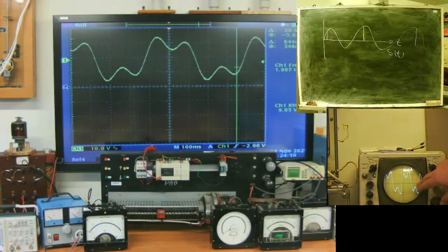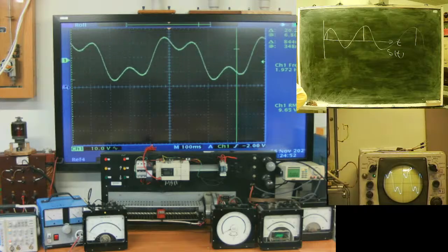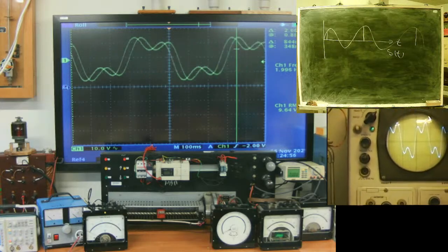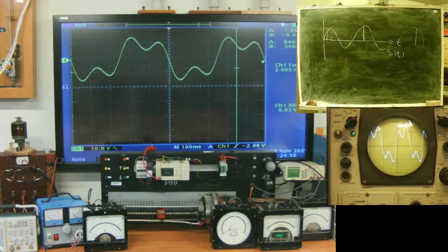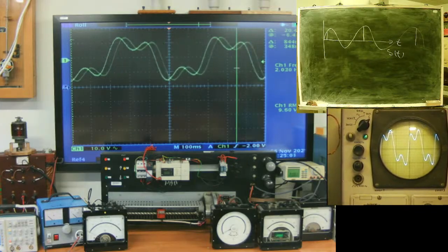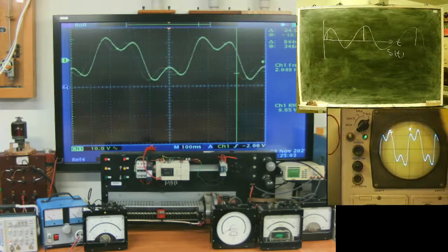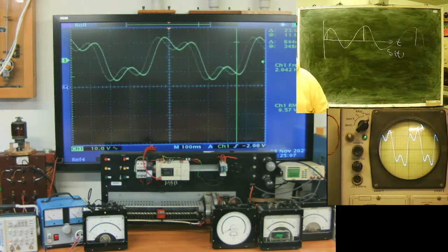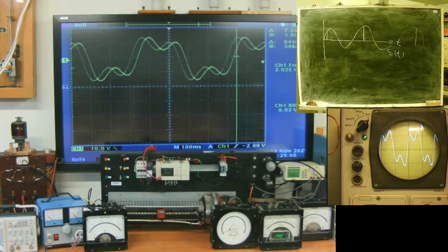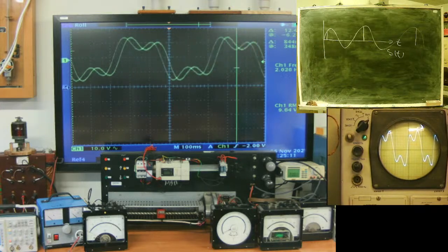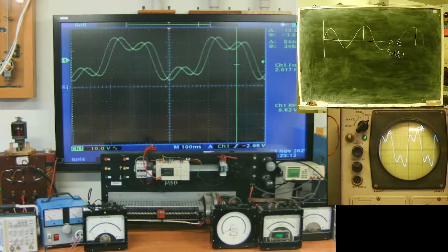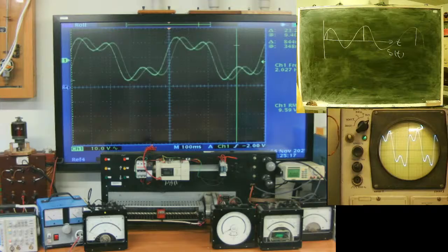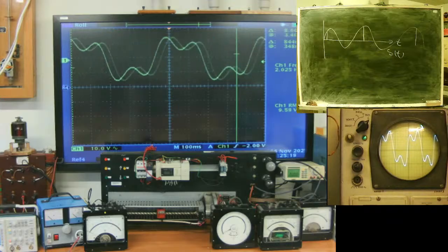True signal. Maybe one second, I will enlarge it. Here is the true signal, and here is what my numerical scope sees, because I'm far right of this border of the Nyquist frequency.